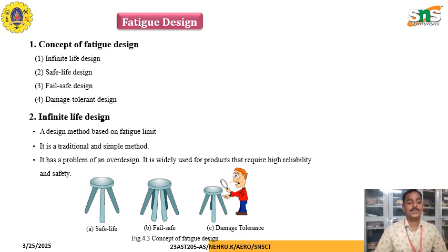These are the four concepts of fatigue design. Infinite life design is a design method based on the fatigue limit. It is a traditional and simple method. It has the problem of over design. It is widely used for products that require high reliability and safety.